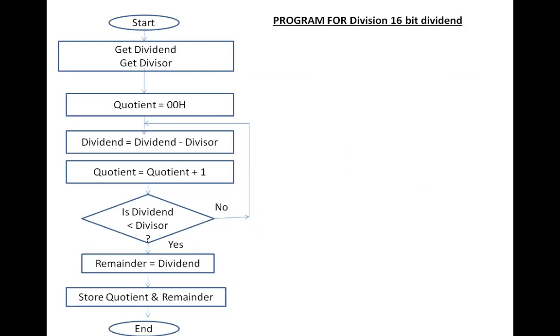As far as the flowchart is concerned, there will be no change at all. But the program will be changed because this time the dividend is big. It is a 16-bit number and the divisor is an 8-bit number.